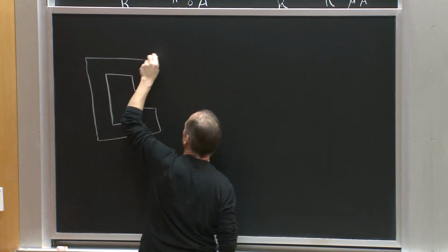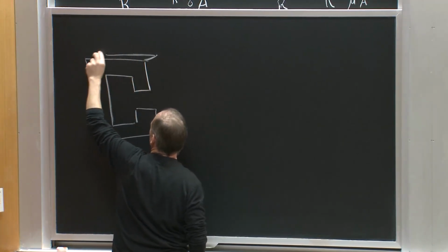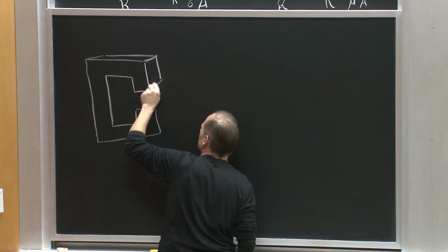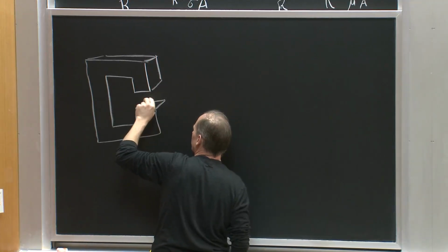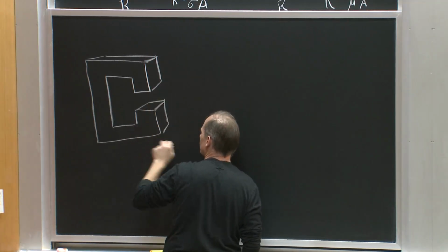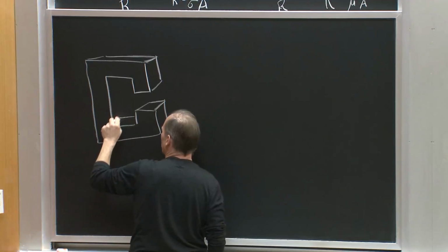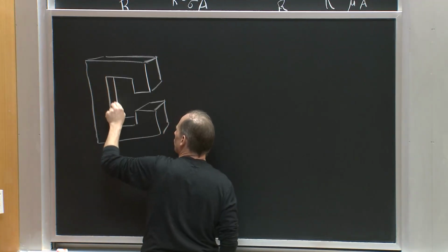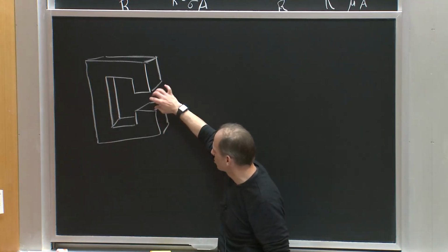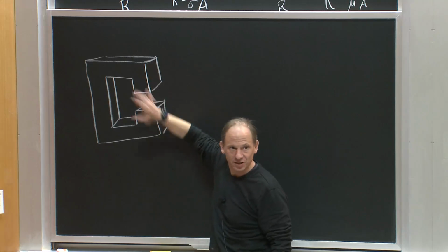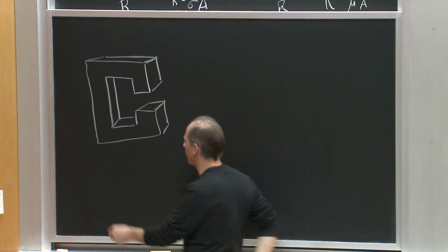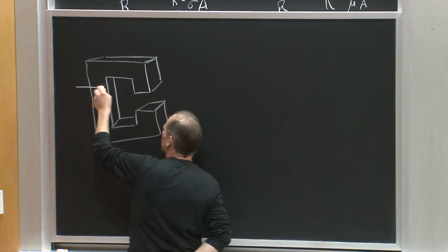We would do that in part because we can make the inductance more stable to material variations, permeability variations. We would also do it because we tend to store energy in the gap instead of in the core material, preferably. And we put N turns on this.